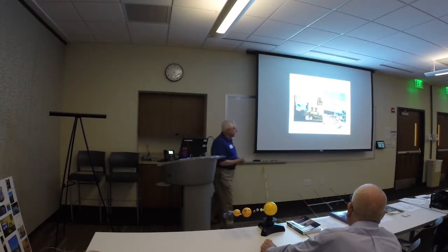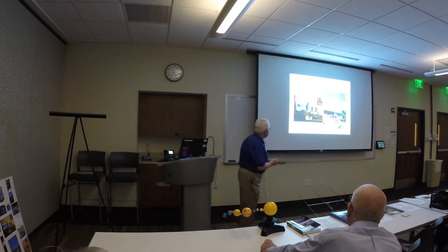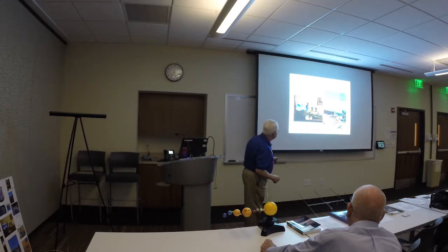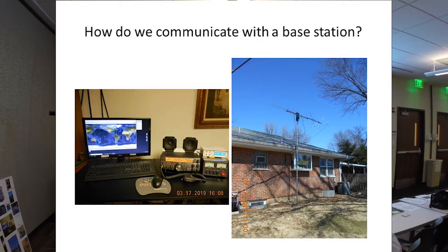This setup that you're seeing here, and it's on one of the boards as well, is my setup at home. You can see, it might be hard to see, there is a UHF antenna, which is a 30 dBi gain, circular polarized antenna, which means as the radio waves come through the atmosphere, the Earth is turning, the spacecraft is moving, you tend to get a spin.